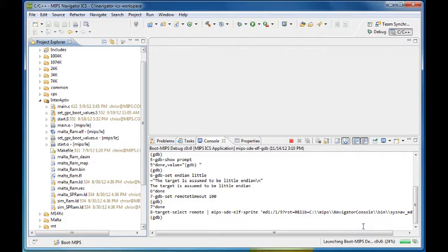So one of the things while this is coming up is the FPGAs are set up that when you have these probes attached, only the first CPU actually is powered up. So as we did in the boot code, we brought up the first CPU and then we actually powered up using the software to power up the remaining CPUs. So we have to kind of do this in a specific order. We can't start debugging a CPU if it hasn't been powered up. So we're going to have to actually run CPU 0 to a certain point before we can power up CPU 1 and CPU 2 and CPU 3.